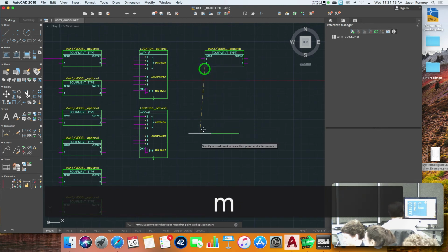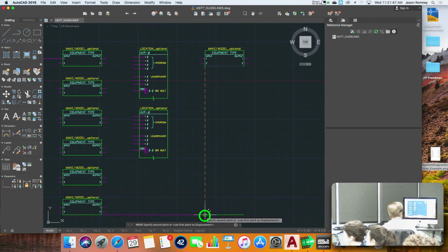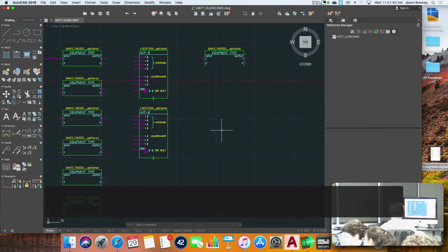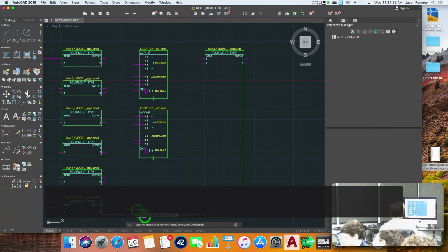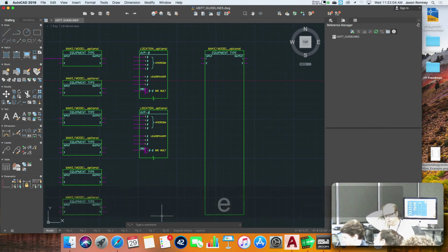And now I can take this, move it down here, and then I can extend. Boom, boom. That's the safest way to extend, and then you can delete this guideline. Safest way to do it, because then you know that it's definitely vertical. The stretch handle can cause you trouble. I can't tell you how many times I've seen people use that, and they end up with crooked boxes because it doesn't always behave the way you think it will behave.